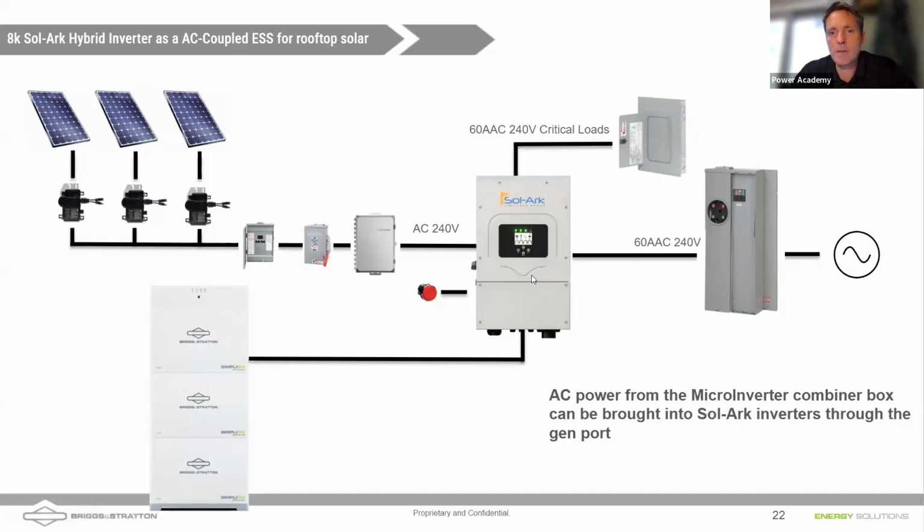And so we have AC power available now to keep the microinverters on, and they do what's called grid following. And so they're going to follow the microgrid that the solar creates and keep power coming both from the solar and from the battery to feed loads. If there's excess solar power, those batteries can charge up from that AC coupled solar array. And so we've got backup power now by adding the solar converter to this system.